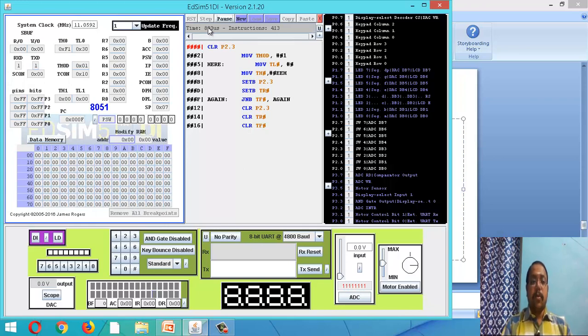So you can note down here. At home, if you do this, you can sit and see here till it reaches a value of 5 milliseconds. This will run. We have calculated it such that now it becomes 1 millisecond, so you have to wait for the remaining 4 milliseconds. Once this becomes 5 milliseconds, automatically the value which you have set as 1 will become 0. So the task is completed. You can say that your program will generate a time delay of 5 milliseconds.